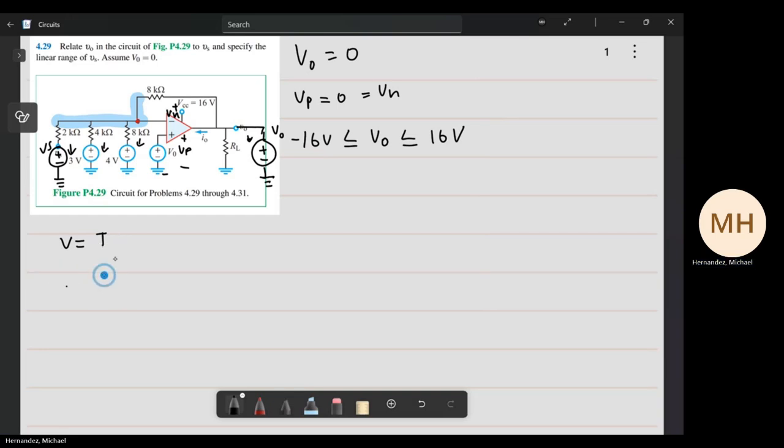And so when we perform this circuit, we're going to use VP for this. So we can do VP, start right here. And because I said that all the grounds are connected to each other, we could travel right here and go to this VS. VS is with a negative terminal, so it's going to look like VP minus VS, and it touches this 2K ohm resistor. It's all just over 2K ohms.